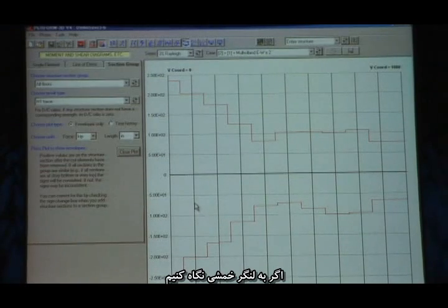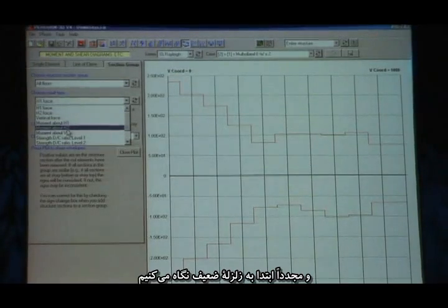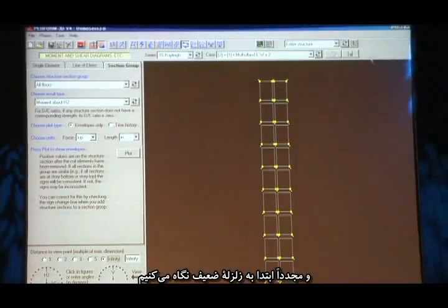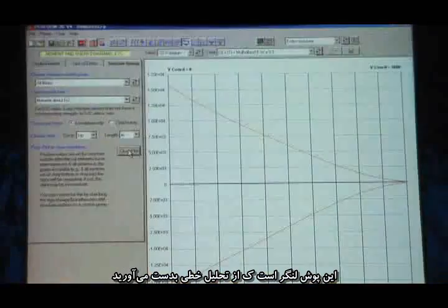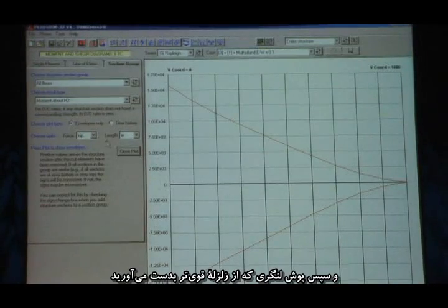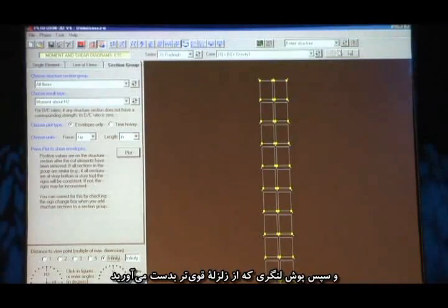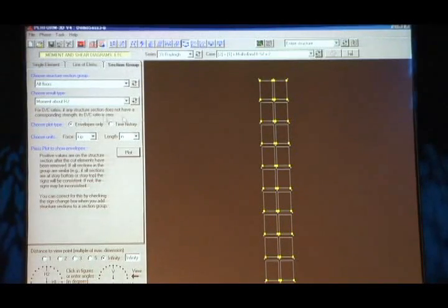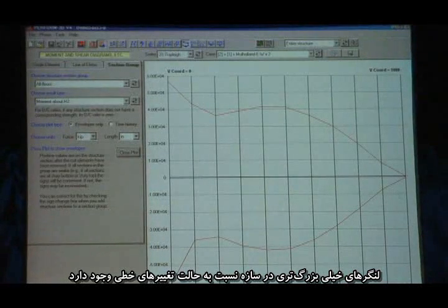And if we look at the bending moment, and again, if we look at the weak earthquake first, this is the moment envelope you would get from a linear analysis. And just look at the general shape. And then the moment envelope you get from a stronger earthquake: very different shape. Much larger moments higher up in the structure rather than the linear variation.